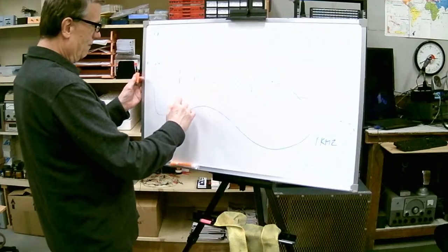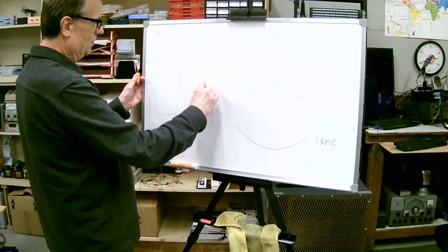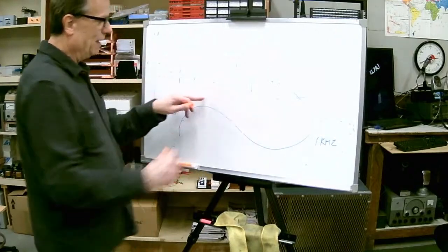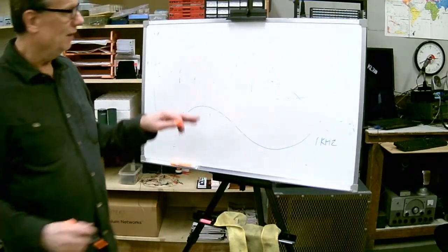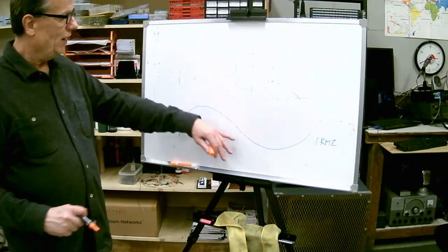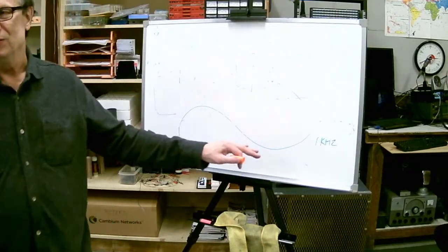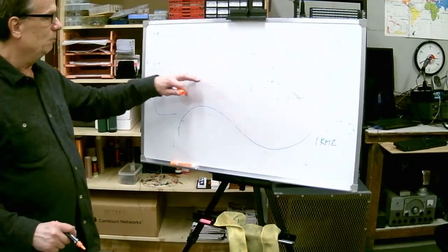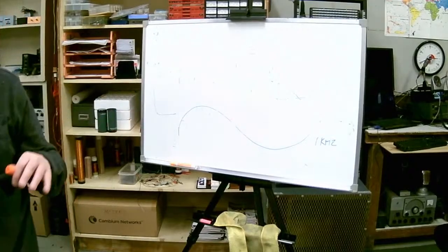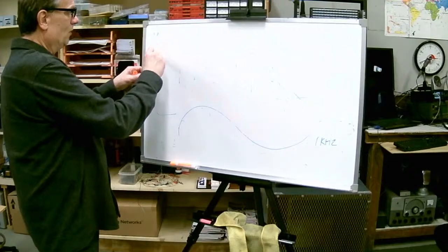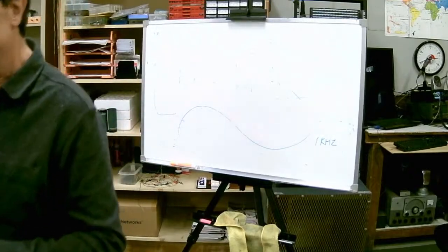All we'd have is a carrier which moves up and down, but the amplitude would stay the same. So in order to get the amplitude to change in accordance with the input signal, we don't do the arithmetic addition, we do multiplication. This little symbol is an actual mathematical multiplier. So we're actually multiplying one signal by the other.